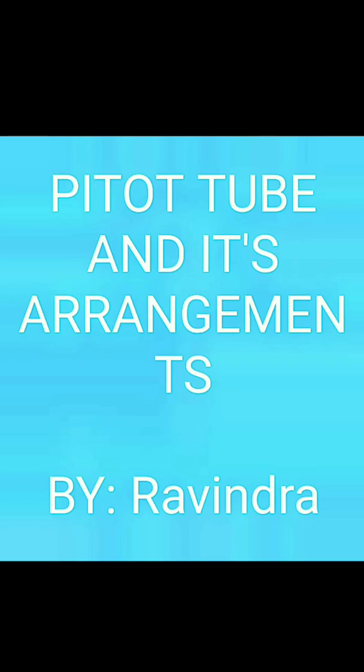The pitot tube was invented by the French engineer Henri Pitot in the early 18th century and was modified to its modern form in the mid 19th century by French scientist Henry Darcy. It is based on the principle that if the velocity of flow at a point becomes zero, the pressure there increases due to conversion of the kinetic energy into pressure energy. So this is the basic working principle of the pitot tube.